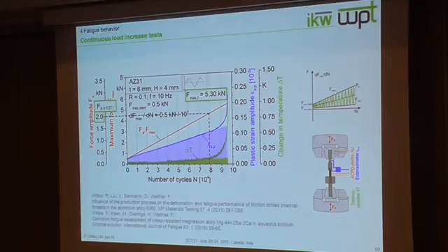And if we estimate the fatigue limit, of course, we have to validate them in constant amplitude tests. This is not what we've done till now, because the project started at the end of last year. So we're going to do this, of course, but we can show in other works that it works for this kind of friction-drilled aluminium alloys and also for magnesium alloys for standard material specimen.